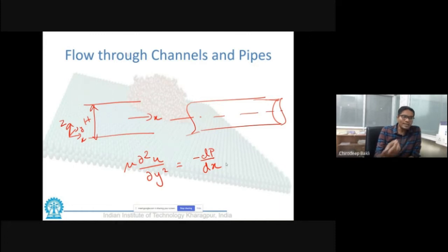But the point that I want to bring home is that this equation is a second order equation requiring two boundary conditions. So just by analyzing the geometry, we try to put one of the boundary conditions as the surfaces of the pipes or the tubes being solid, and a solid geometry would not allow a penetration across the surface. So no fluid would come out of this surface, hence making the velocity in the z direction at this point to be 0. So that gives the first boundary condition.